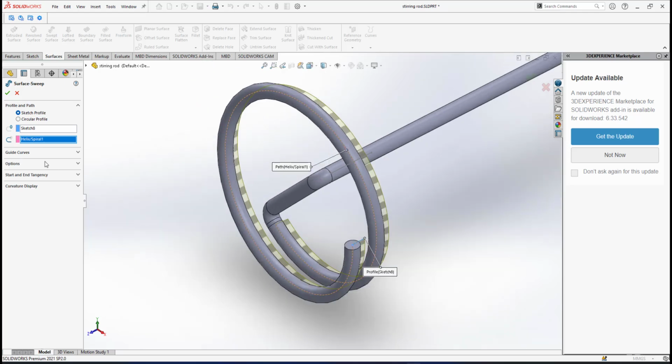But here, if you look under the setting on the left, under the profile twist option, I'm not using minimum twist angle. I will go for specify twist value. Under specify twist value, I can play around with the degrees. For example, one revolution is 360 degrees, 720 degrees is two revolutions. I'm not using by degrees, I'm going for revolutions.